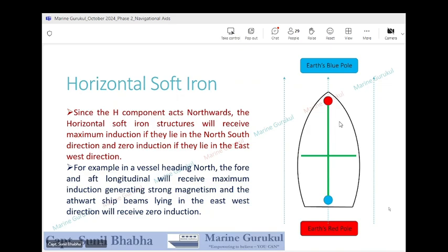If you compare this longitudinal with a deck plate or a keel plate or ship's hull plate, you will see these plates are built in the foundry, but when they are brought to the yard, first they have to be brought into shape. The hull of the ship is curved, so they have to be bent in that curved orientation. It's a 3D kind of bending.